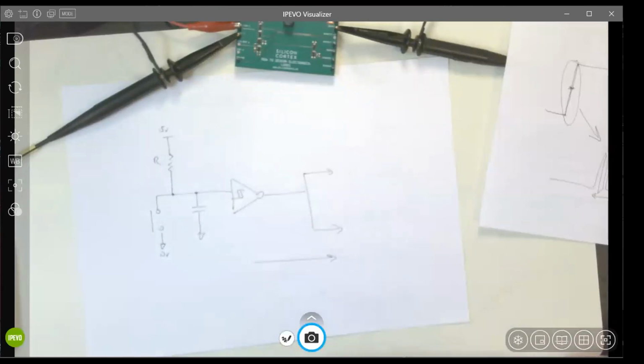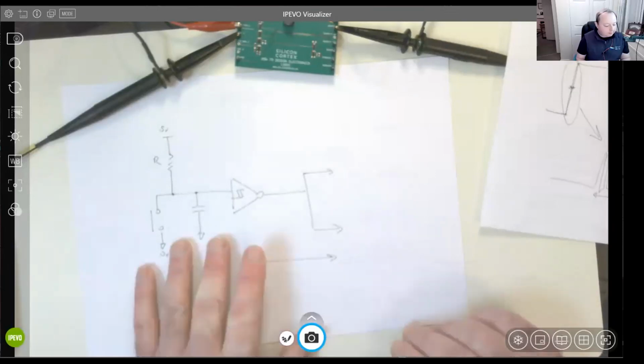I think at one point when I was working on a Centronics connected printer, because the decoupling network was wrong at the other end, the strobe line was ringing like a bell and flying way past the TTL trigger positive when it should have been driven low, swinging way into negative, swinging way back up past the TTL positive trigger, and settling out over quite a long period. It's one of those things where it might be quite a good idea to have a Schmitt in there. So I'm glad you mentioned ringing.